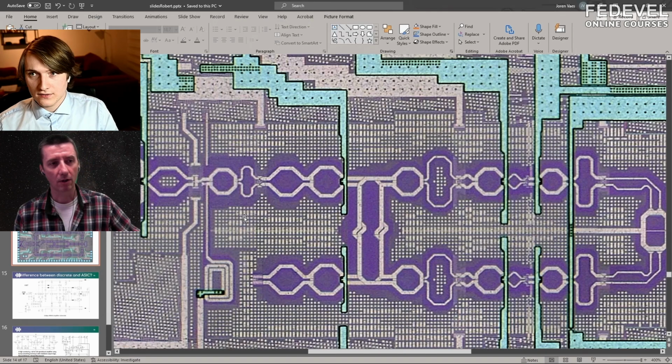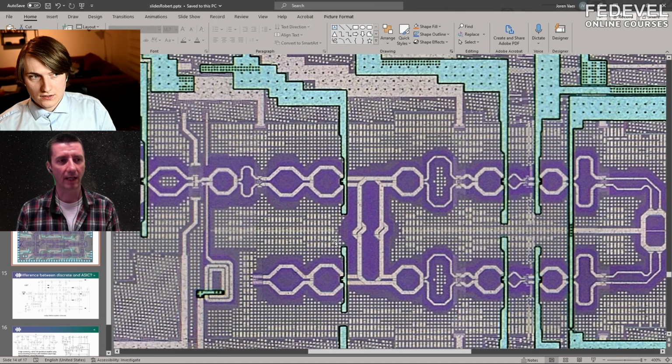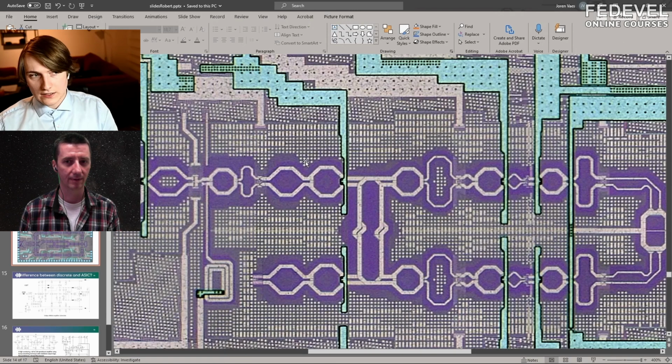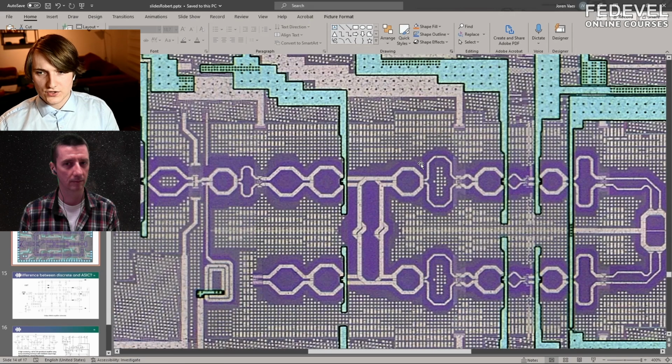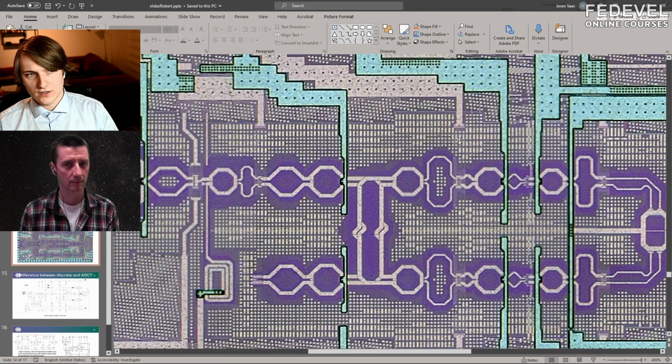And sometimes, is this not going to influence the functionality of...? It will. And that's why you include this to some extent in the modeling. So for some of these inductors and transformers, you might run another simulation after you add the dummies to make sure it's still correct, especially where it's very critical, like a VCO inductor, where it might be very important to know exactly how that inductor behaves. You would simulate again with these dummies.